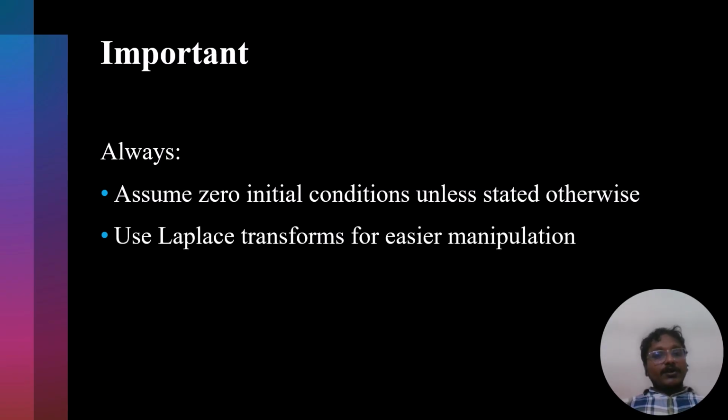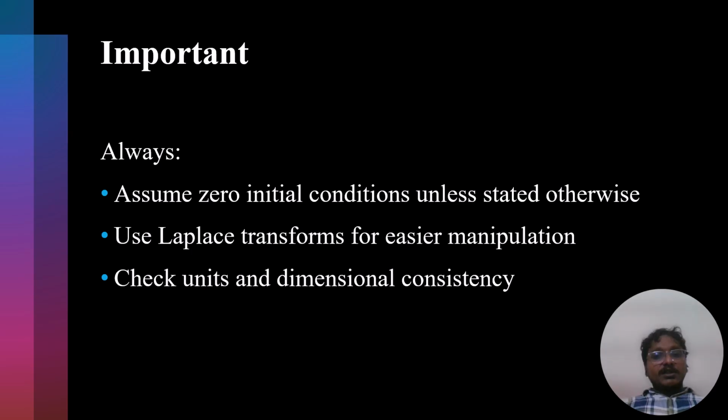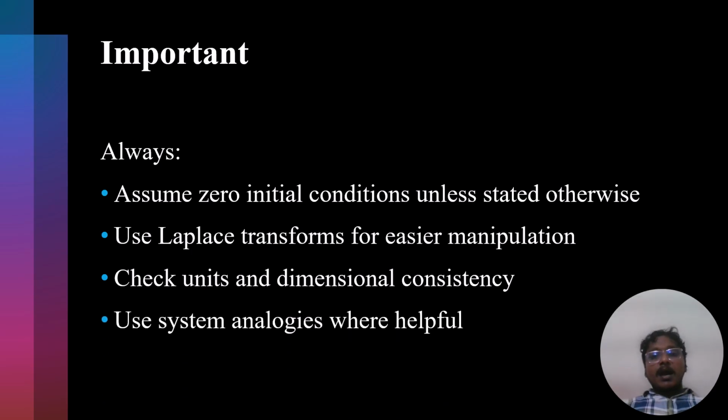Next, use the Laplace transform for easy understanding and to reduce a big equation into a smaller one, which helps reduce the equation format. Also check units and dimensions consistently. In system analysis, such as mechanical to electrical, electrical to mechanical, rotational to mechanical, and rotational to electrical, these things are very important when writing the transfer function equation.